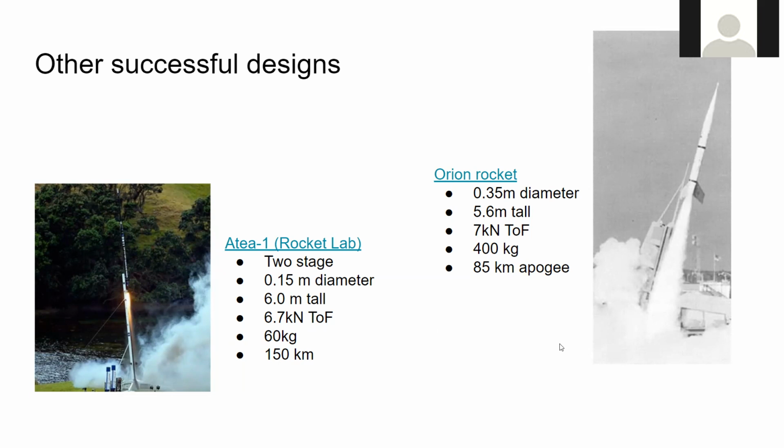And I'm just going to make a point in there. The reason why having 2 stages rather than 1 stage makes a difference is because you can do a very high impulse boost right at the beginning, burn a whole bunch of propellant, and then drop kind of all the dead weight of your rocket, and then just coast with a much smaller section of it. So you have much less drag and much less mass to carry with you, so you're able to be much more efficient. However, one of the rules of our competition is that you need to be a single stage rocket. So that is the condition that we're operating under.